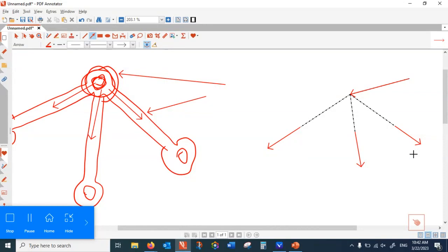All right, so that is the method of joint. The method of joint is a simple method, but it's a limited method. It can only handle two unknowns at a node. Why? The reason is, with the method of joint, you notice all forces are passing through one single point. So that free body diagram does not have any capacity to rotate. You can only impose no translation in X, no translation in Y. But the minute you start imposing no rotation, all you get is 0 equals 0. That's not useful information. So this is the limitation of the method of joint. It can only handle two unknowns at a time.